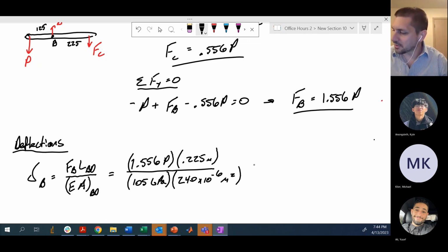Put this all together, and you're going to have some coefficient in front of the variable P: 0.0139 times P. Now the question is, what's happening to the units? Because this can be a little confusing. We've got gigapascals here, which is kind of like a 10 to the 9th sort of thing, and we've got meters and meters squared.